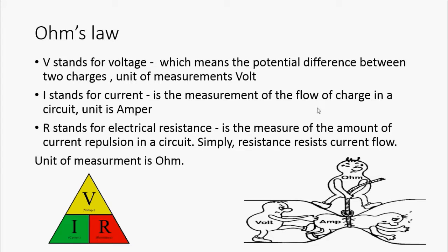But it can also be the difference between positive 5 volts and negative 5 volts, positive 20 volts and positive 10 volts, etc. In the field, you might hear the term common ground, which refers to each device in a system using the same 0-point reference, or ground, to ensure the same potential difference, or voltage, is applied throughout the system.